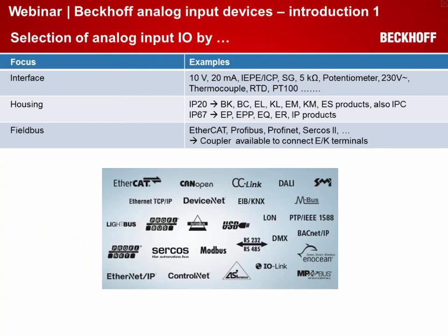EtherCAT itself, invented by Beckhoff, is the technology that we use in the latest measurement devices, but with special couplers these EtherCAT terminals can also connect to another field bus to talk analog data to other controllers, masters, independently from the communication system that is used inside of the I/O modules.